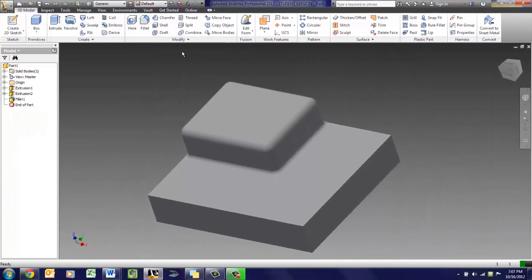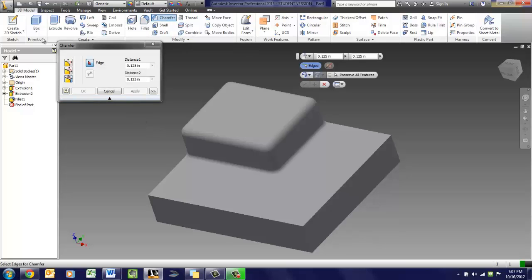Let's actually go instead this time, and let's do the chamfer portion. So let's make some chamfers on this front edge here. All right. So again, under Modify, I'll go up to Chamfer. Okay. And it gives me the option of selecting edges to make my chamfers on. Same drill. Okay. We've got the equidistant double distances here. I'm sorry, that was the distance and distance and angle here, and then we've got the two distances here. And again, a rise and a run.